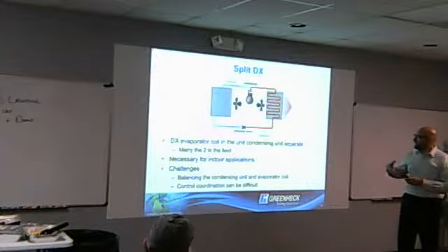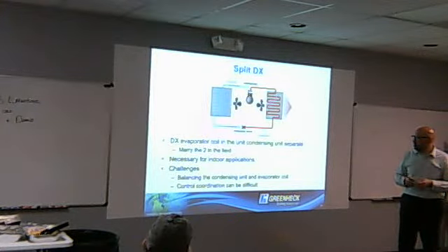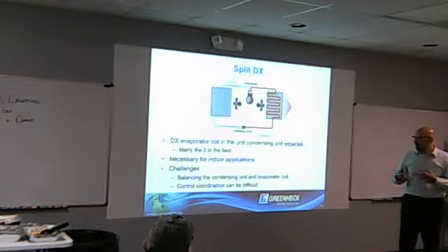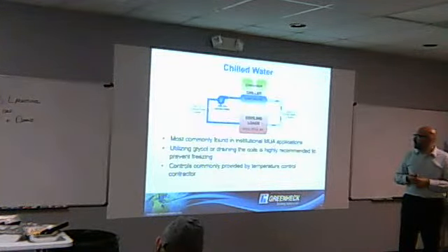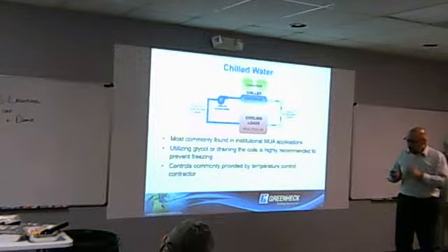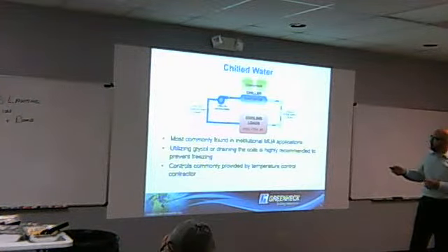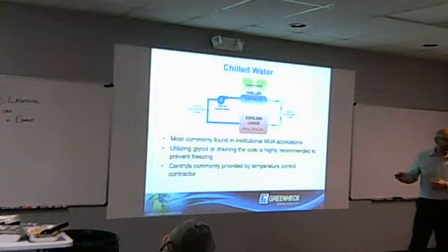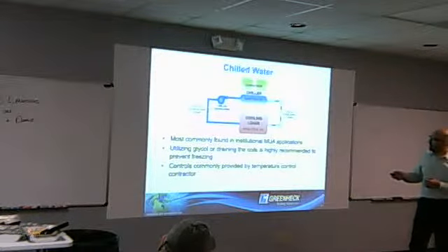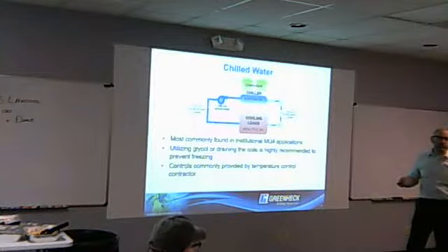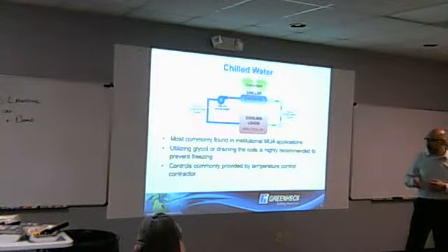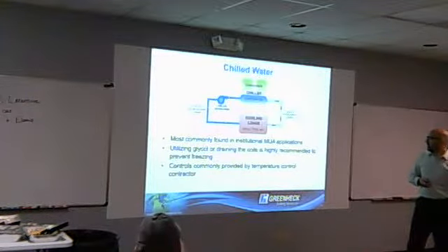And then Greenheck has developed a remote condenser too for some applications, but I don't see a lot of the split DX, but it is possible. Chilled water, excuse me, you're probably not going to add a chiller and cooling towers and things, but if it's there and you say, hey, we already got chilled water, we might be picking a unit for somebody to have chilled water for it. Probably depends on the size too. Yeah, exactly.